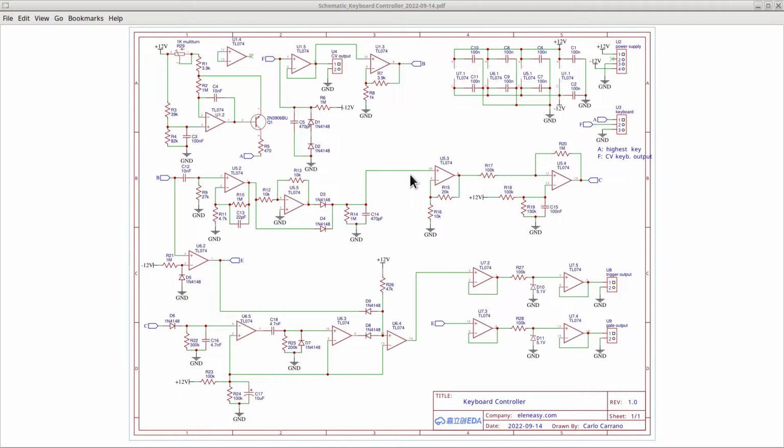Problem is, we could have noise along with these pulses like the one we saw in the previous episode, and it is in fact very likely to find it, since this part of the circuit is still the same. No worry though, we can remove the noise the same way we did with the one in the gate signal. We use a comparator to either have minus 10 volts or plus 10 volts and nothing else. Any background noise will be brought down to minus 10 volts by the comparator.